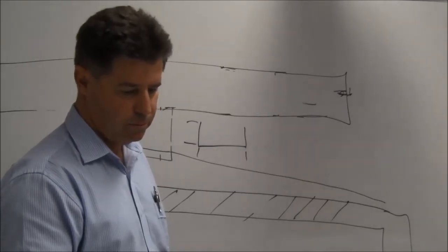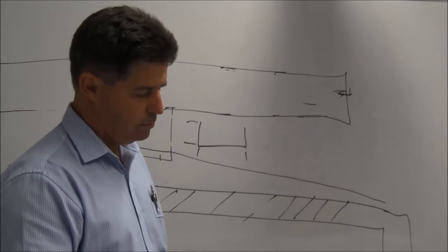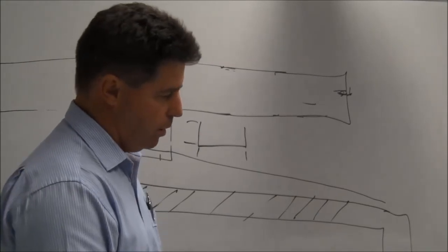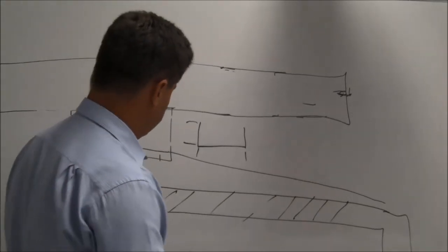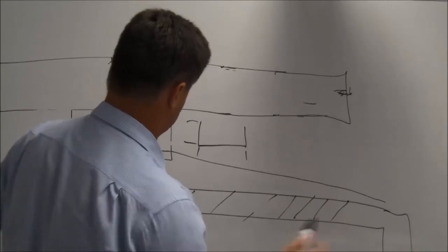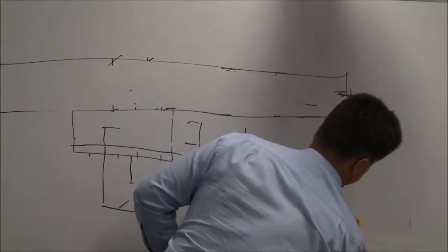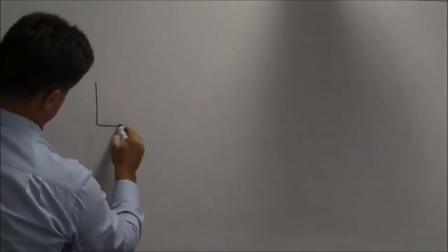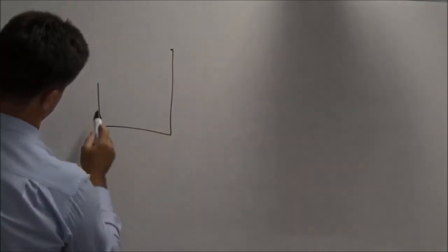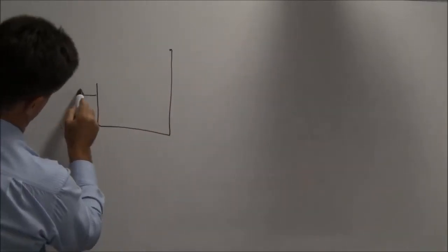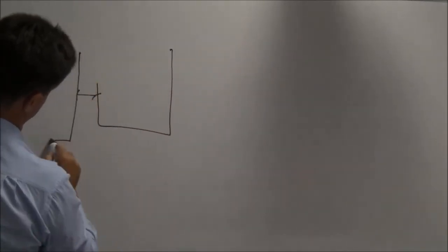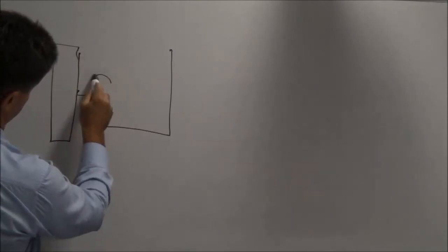And do we have some overflows for the eaves gutter as well? Exactly the same as the box? No, the overflow on all eaves gutters must be... well, you can do it two ways. If you're going to get something made up, and it's going to be something with a high front, for example, you'd have to make sure that the contractor leaves a space at the fascia, so it can overflow out through the back.